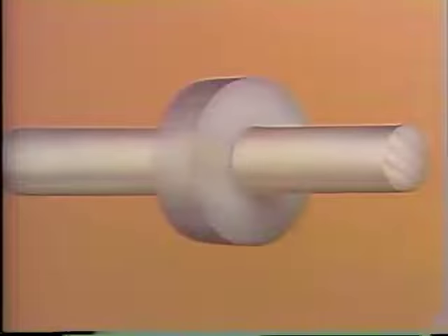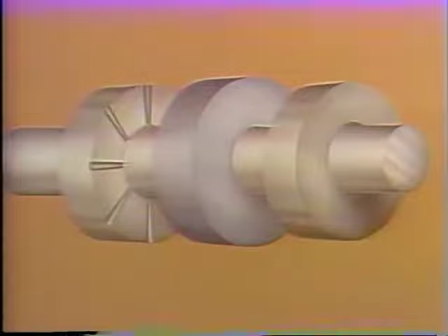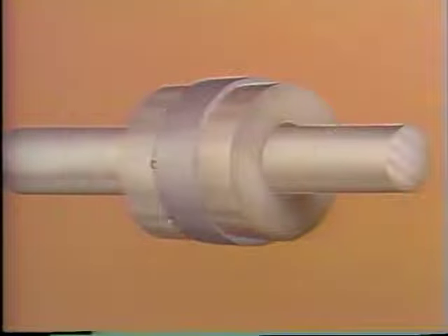In this case, a thrust bearing is used. This bearing can also be called an axial bearing because it's designed to prevent axial movement of the shaft. Here's a shaft. Attached to the shaft is a raised section called a collar. If the shaft moves, so will the collar. Around each side of the collar are bearing surfaces. They fit around the shaft without touching it and are slid up until they contact the shaft collar.